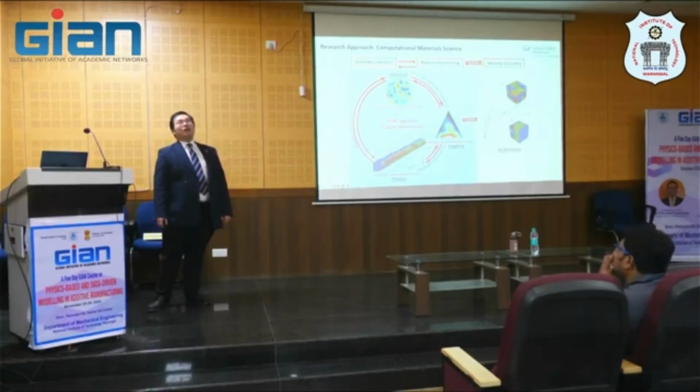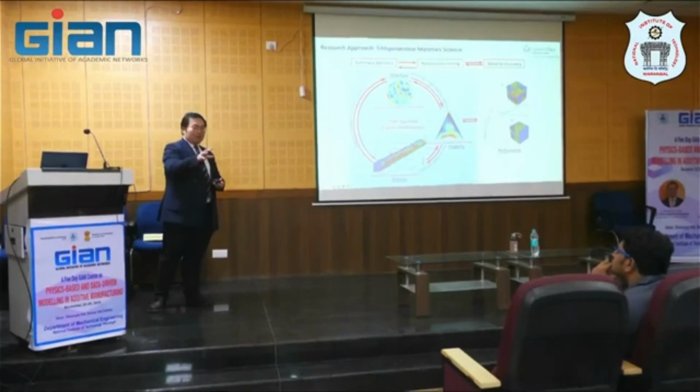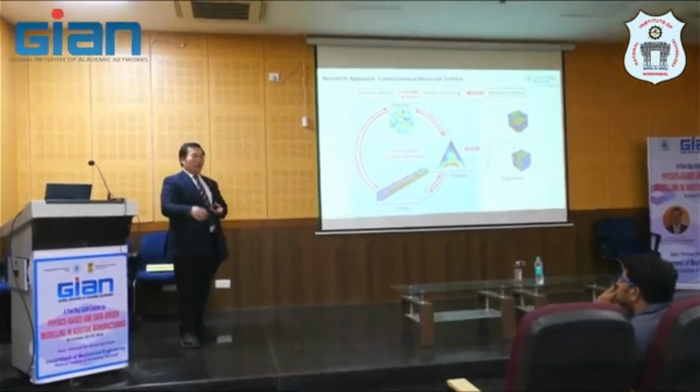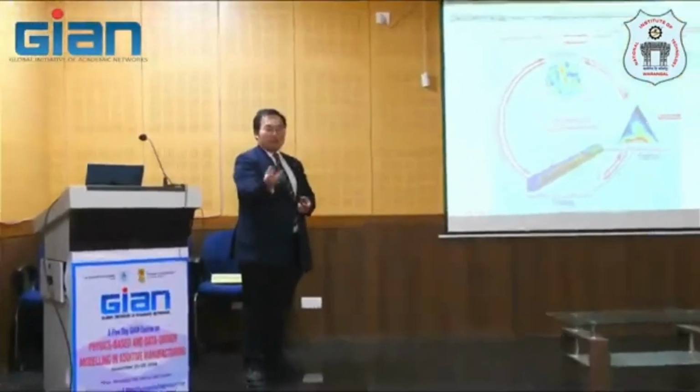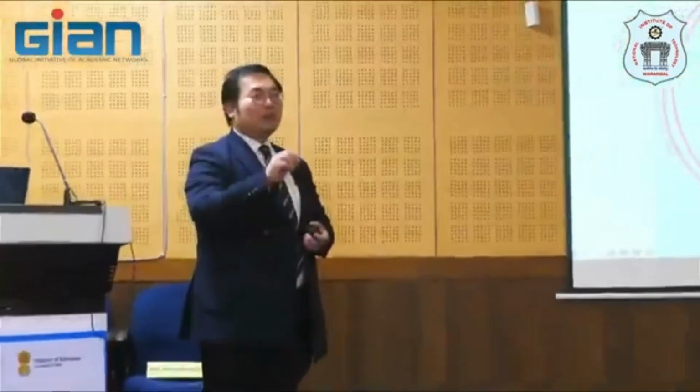So I think the key thing is that we're not going to bang our powder bed with high energy to make sure that everything fully melts, because you will introduce keyhole defects. You just want to go to the boundary of the conduction and keyhole mode. That is the optimum condition where you can melt it with as minimal defects as possible.